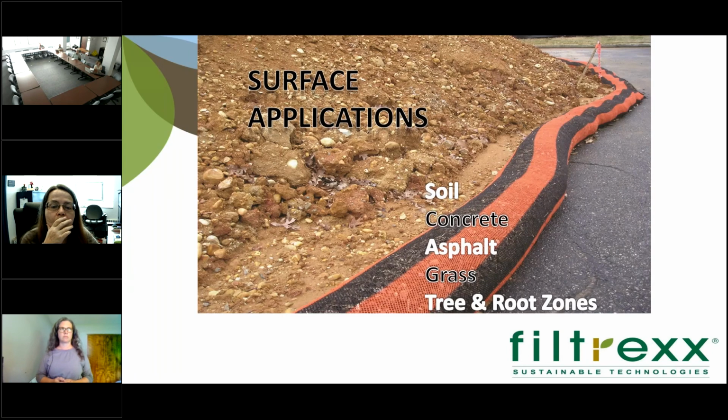The other thing that's nice about the silt sock is you can lay these on a hard surface. You can lay it directly on concrete or asphalt. We've done this many times. As you can see here, there's a pile of spoils. You can lay your sock right on a hard surface, and it'll do its job just as well as it would laying in the grass.